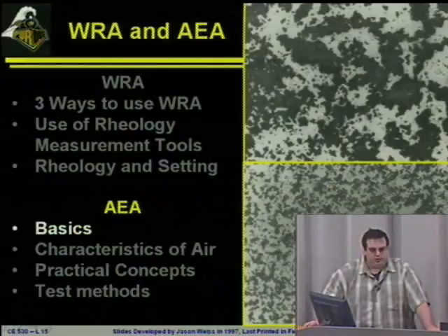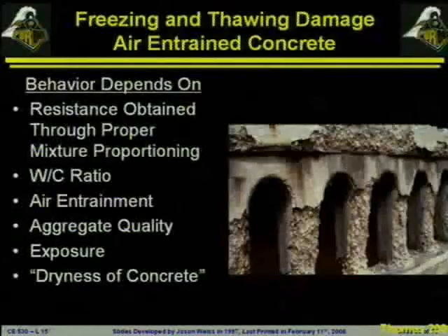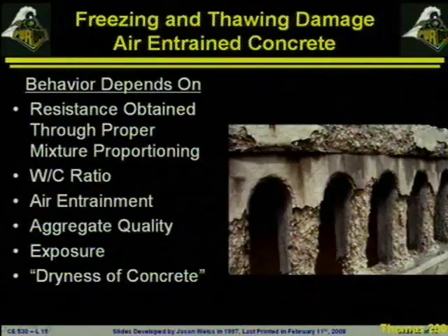Jumping ahead to air entrainers. Some of the basics. We've talked a little bit about the basics and the need for air entraining in concrete. What I want to do here is talk a little bit more about some of the other factors that are going to influence air entrainers, in addition to just their overall volume, and then some of the other aspects of these mixtures that are important when we start to talk about freeze-thaw resistance, which is obviously going to be related to mixture proportioning.